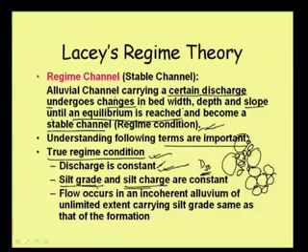So the total concentration of bed load and suspended load we call the silt charge. How much silt charge is coming is important. But in Kennedy's theory or Lacey's theory, we are not using any parameter to take care of this silt charge. We are just considering that it will be in regime condition when the silt charge flowing through the channel and the silt grade are constant.